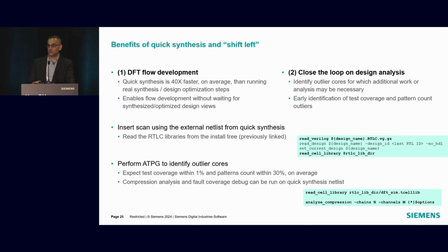Debug and verification of what you have to do at the RTL helps tremendously. And there are the more detailed commands. The last major bullet on this is performing ATPG to identify outliers. You can also use analyze compression, which is the command in the tool that you can use to do experiments to see what kind of configuration you need for EDT and what gives you the best results. You can do all of that at RTL.